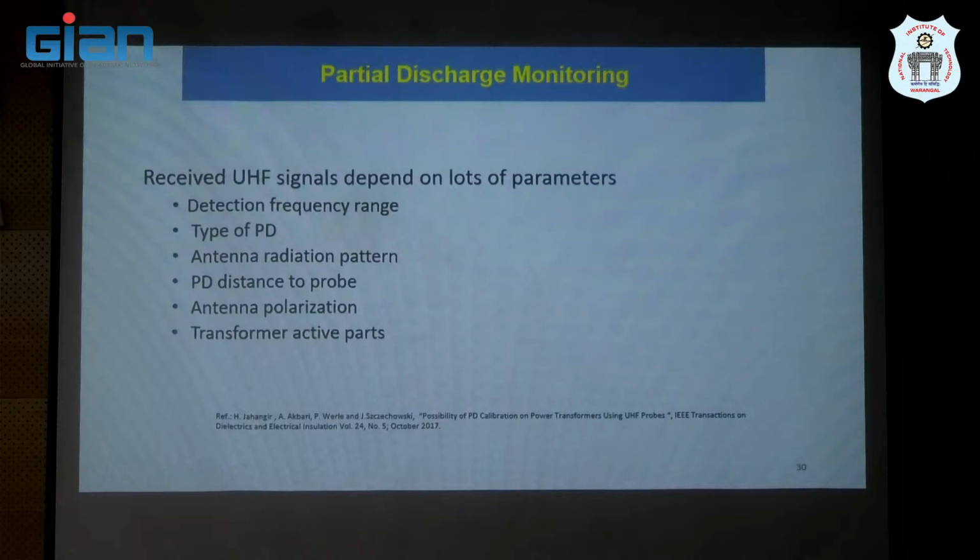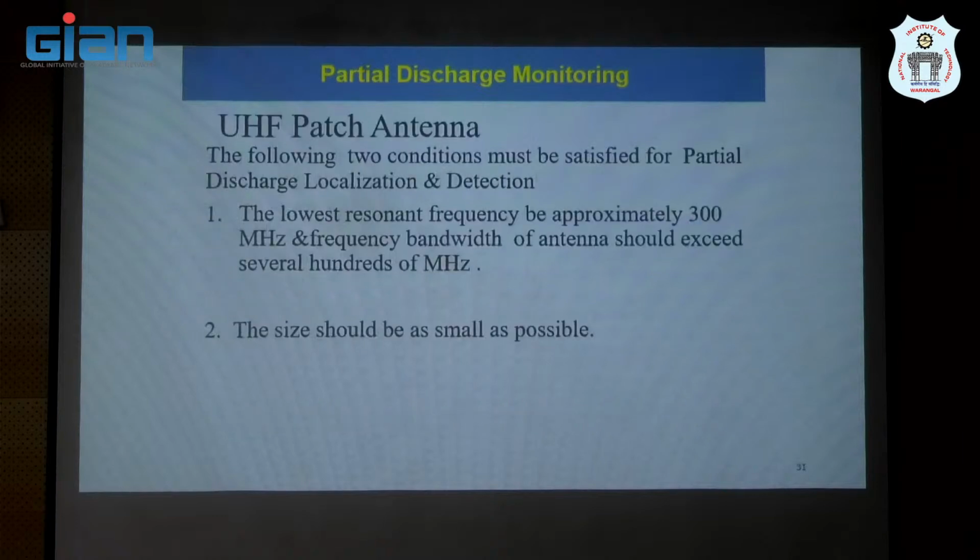So these are UHF sensors. The type of PD, detection, frequency range, radiation pattern, these are the parameters. There are different antenna designs, like narrow band and wide band antennas, that we can also use. It depends on the application, how we want to go for the design.